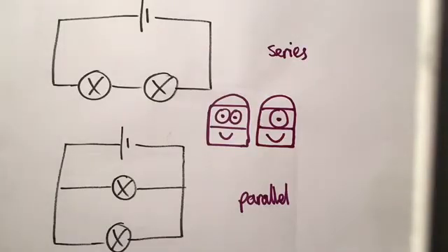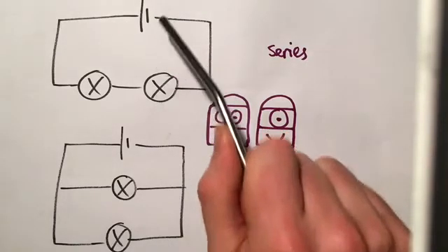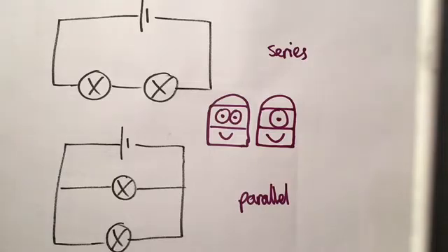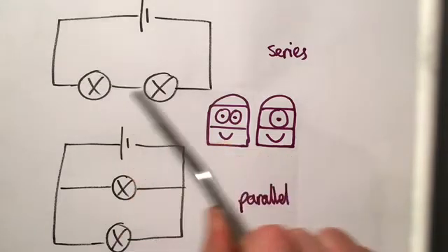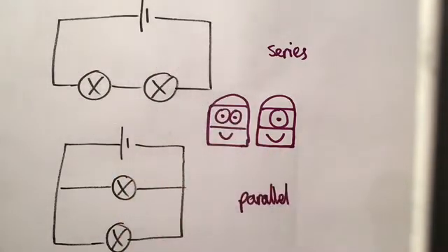So here we've got two very simple circuit diagrams. We've got a series circuit and a parallel circuit. Both of them have one cell and two bulbs. So let's imagine, to start with, that we've got our minions, our charge carriers, our electrons flowing around this series circuit here. Our charge carriers all gain their energy when they pass through the cell.